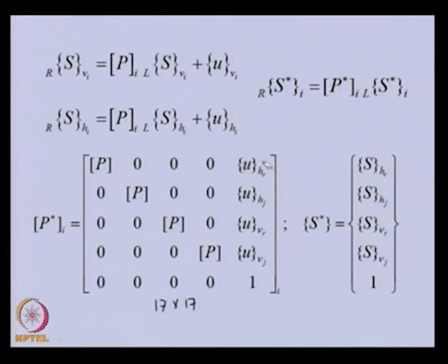Here we have the component of the unbalanced force in the vertical direction or horizontal direction, real part, imaginary part, real part, imaginary part of the vertical direction. So, here additional external force vectors are coming, and these are from the unbalanced force.